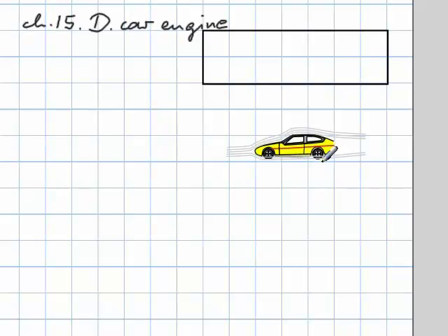Why are we doing that? Because the equation becomes rather simple for the efficiency. In an attempt to increase mileage performance, an inventor builds a second engine that functions between the exhaust and outdoor temperatures and uses the exhaust heat to produce additional work. Assume that the inventor's engine can also be treated as a Carnot engine. Determine the ratio of the total work produced by both engines to that produced by the first engine alone.